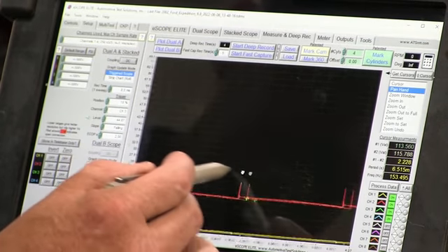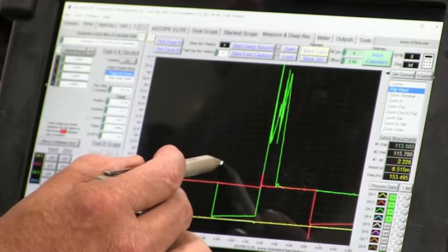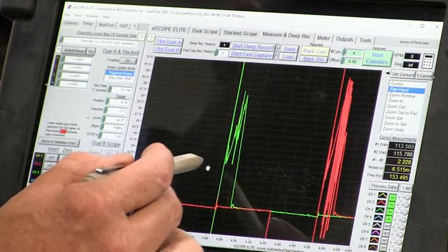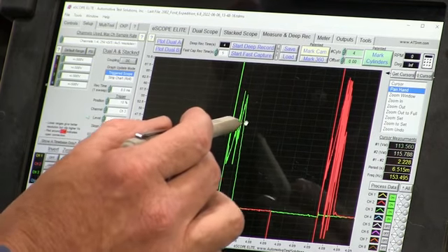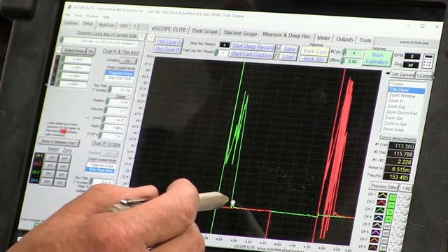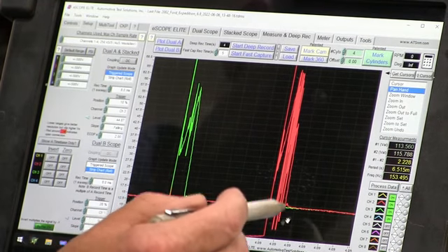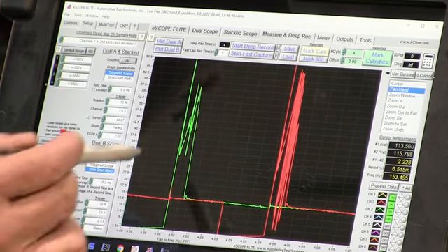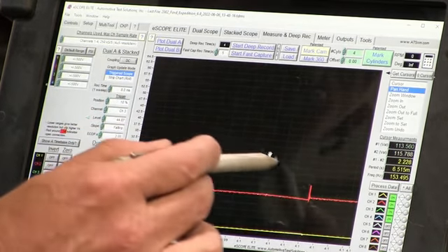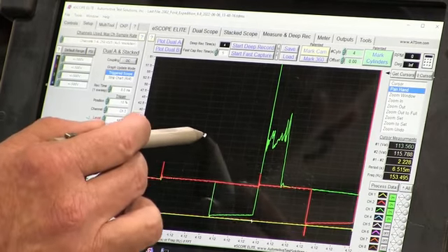So we still have some lean cylinders, but when we're snapping it that hard, we're doing pretty good right now. And here 9 looks okay. We've dissipated most of the energy across the burn. Very little negative going tail. 1 has a little bit bigger of a problem, a little bit harder. 1 looks like it's still a little lean. I think 9's going to be okay now though. And 9's the one I'm mainly worried about because it's the one that carbon traced.